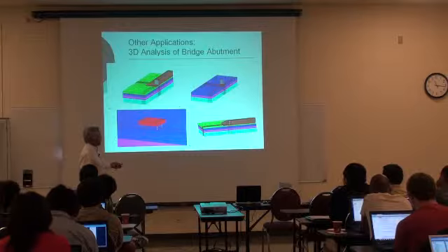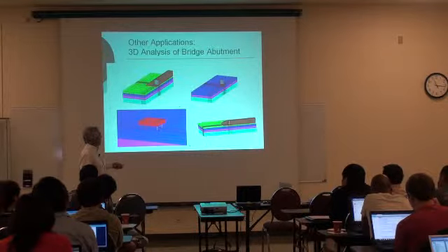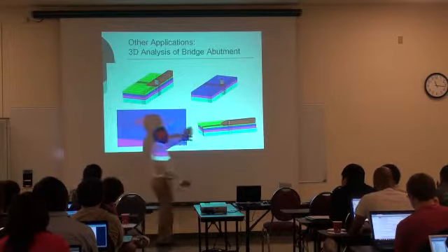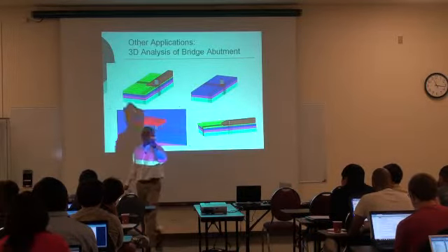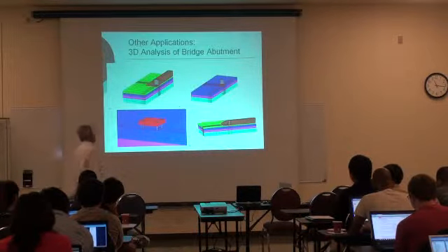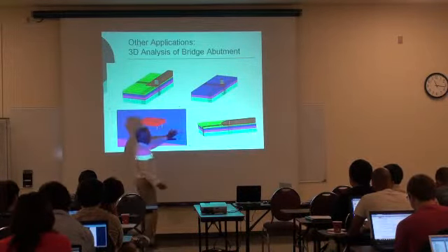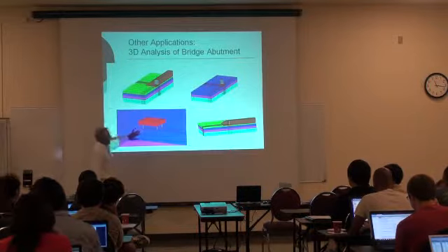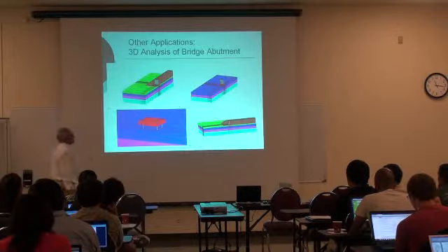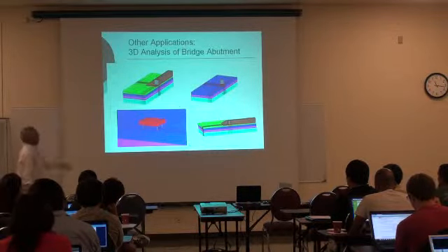We have a more refined mesh, and then we have started with this one. When I say that meshing is an art, the best thing that you can do is to develop a mesh that you can refine. That's what you have to do. So what we did is to put a lot of time in trying to develop a mesh where these elements can be made smaller. So this has around 150 to 200,000 degrees of freedom.